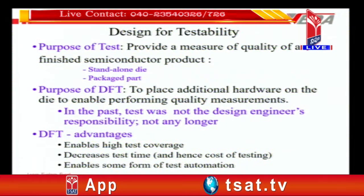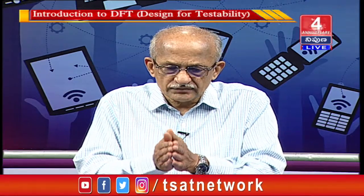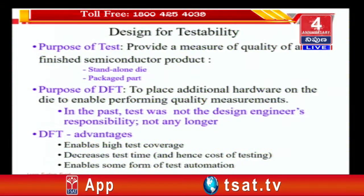Decreasing test time directly translates to decreasing the cost of test, because the cost of test is also included in the chip cost. Okay. And methodology enables some form of automation. As I said, automatic test pattern generation. Okay, they will generate the vectors for you. You do not have to worry about generating the vectors. Okay, they will generate the vectors based on the netlist that has been fed to them, after it has been modified in such a way that it becomes easily workable for the tool.